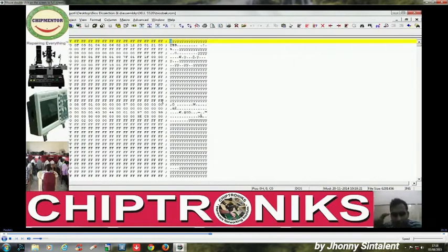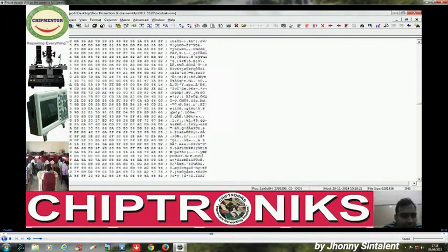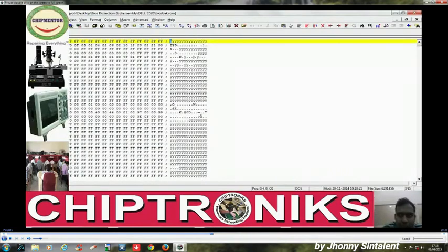As I said, the first 4 MB is system BIOS, so we'll select the first 4 MB and delete the remaining to get our system BIOS. 4 MB is 00, you see 00H2 003 3FF. You can see over here. We'll select the first, EFFFFF.